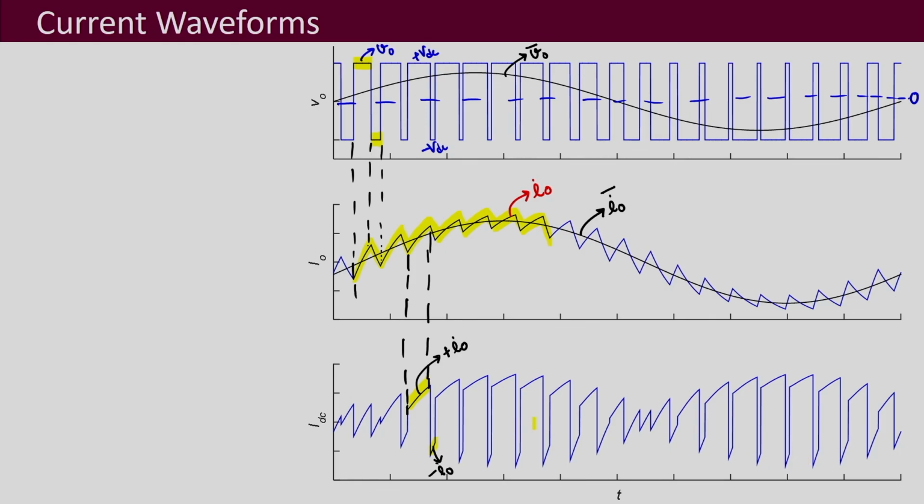And what we see is that it is a very switched current waveform, so it has several components in it. One component is the DC that will be there, which is your IDC, and then it will also have the second harmonic component, that will be your IDC 2, let us call it.